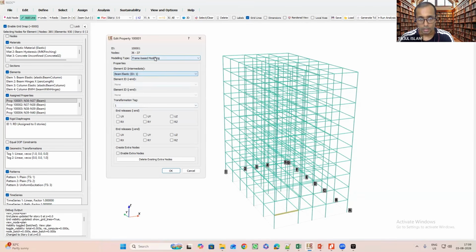Here you can select either frame modeling or fiber modeling or other modeling type. For beam, we are choosing the frame modeling, like elastic beam column element. Then accordingly, which element you want to assign to this member. So this is the beam elastic. This we are going to assign here. And if you are building the nonlinear model, you also enable the plastic hinges. Okay. So it will define some extra nodes required for connecting the plastic hinge to the elastic beam. Then you have to define the hinge for both ends. Okay. So we are assuming same properties for both.